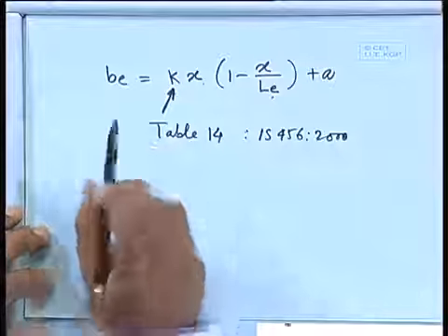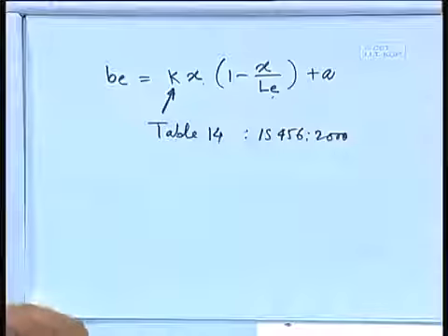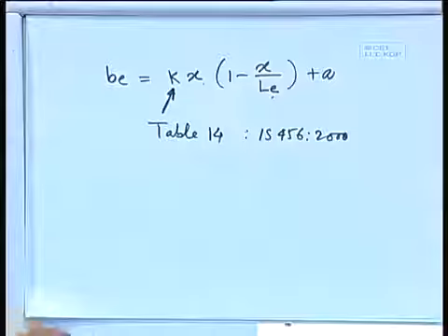So, due to concentrated load, we have to calculate that effective width instead of taking 1 meter width, and we can find it from this formula, which is also available in the code. Similarly for the cantilever beam also. So we shall stop here, then we shall continue the slab in the next class. I think we shall take a few more classes for slab.